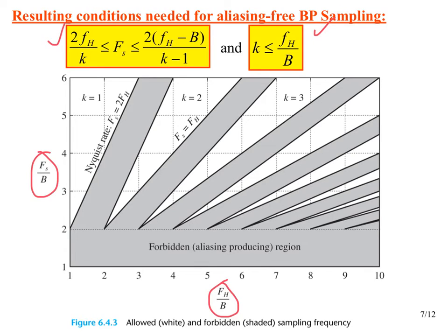So if we're operating down here in this region, and it continues up, that's regular sampling. All the others are some form of bandpass sampling, and as we go this way, we're going to more and more extreme nature of bandpass sampling.